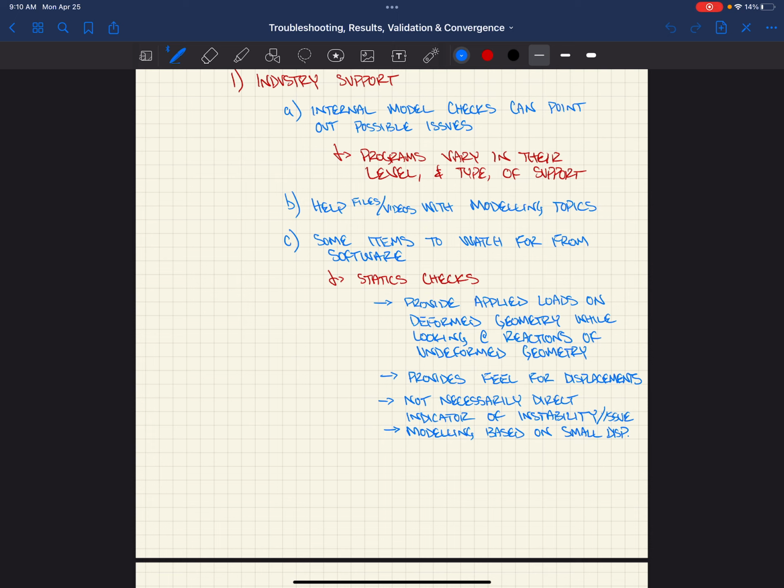Because you might have a load case or a load source, dead load's one thing, but if you had a load case where you have dead plus wind, like the 0.6 dead plus 0.6 wind, or 0.9 dead plus wind, and so you actually get a model that's displaced, like if I looked at this one here, should have those in here. Maybe the model's not displacing enough. You might end up getting some change in the applied force versus the reactions.